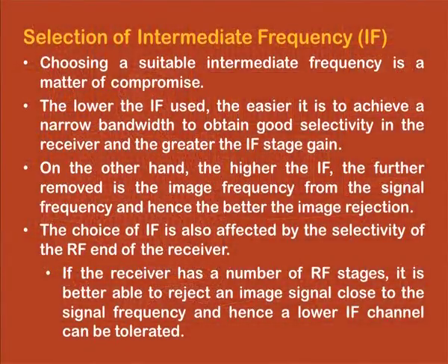This choice is a compromise between several pressing needs which all have to be met to a satisfactory level. So, what we are going to discuss here is the criteria which must be followed for selection of intermediate frequency. The lower the IF used, the easier it is to achieve a narrow bandwidth to obtain good selectivity in the receiver, and the greater the IF stage gain.